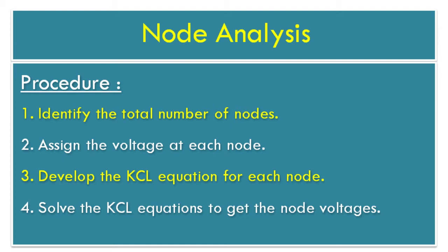We just studied KCL and sign conventions useful for node analysis. Let's study and understand the procedure of node analysis. Procedure. Step 1. Identify the total number of nodes. Step 2. Assign the voltage at each node. Step 3. Develop the KCL equation for each node. And step 4. Solve the KCL equations to get the node voltages.